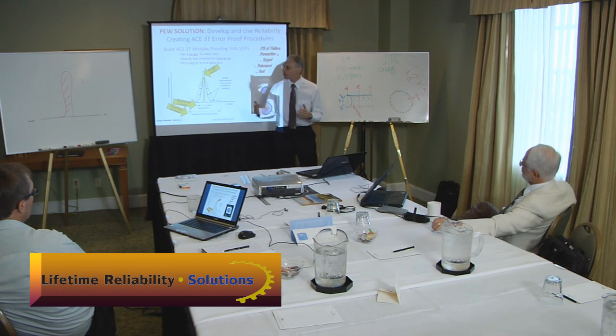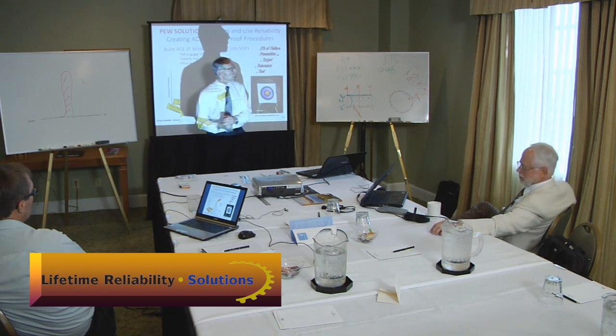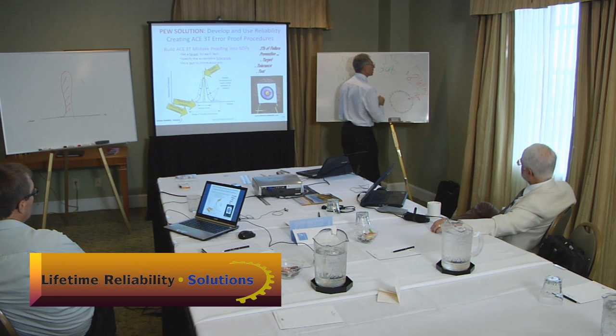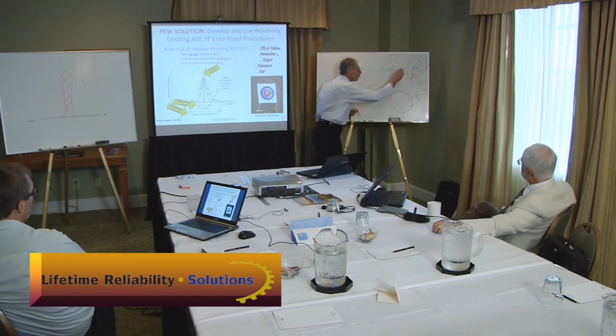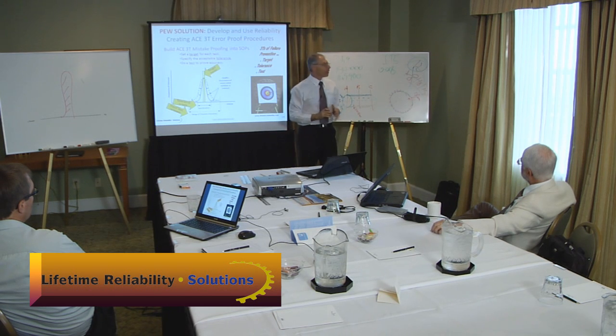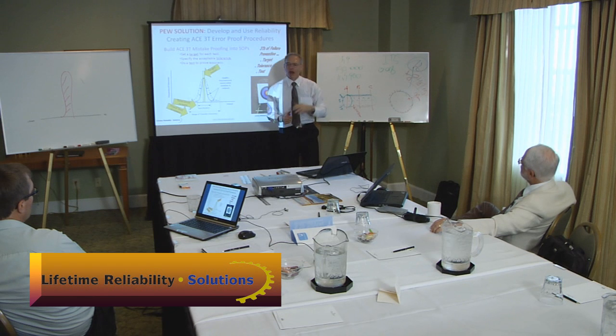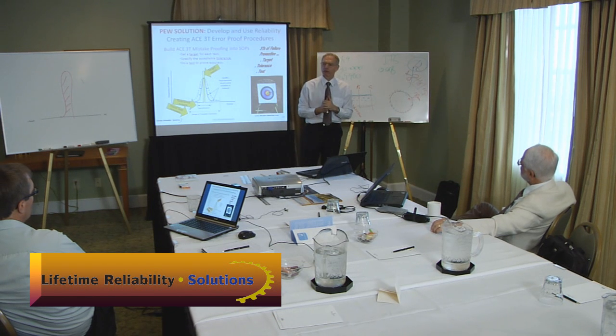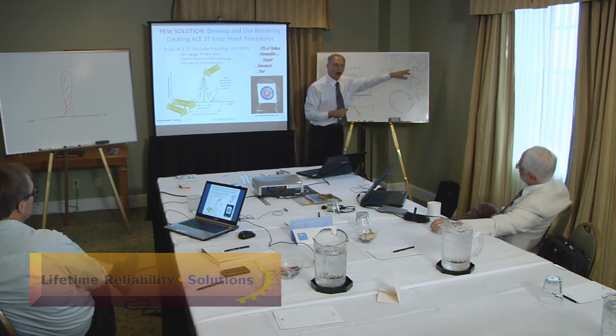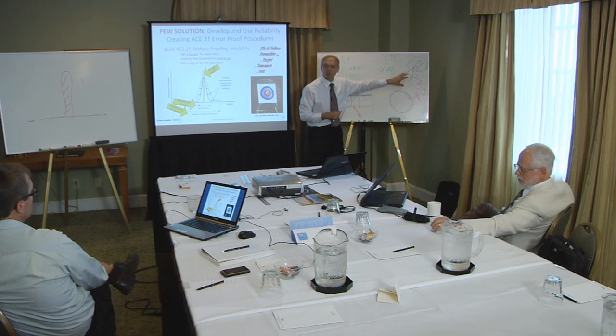And how do you solve that? Well, you've got to have quality control. So what standards must I have? Gee whiz, give me 12. Give me 12. That will create reliability. So Mr. Manufacturer, install on your hydraulic systems kidney filtration as part of your supply to me. If you don't install it, I'm going to install it myself. I'm going to spend the money to put kidney filtration on that unit on purpose. Because that 12 from 18 is 5 less breakdowns.